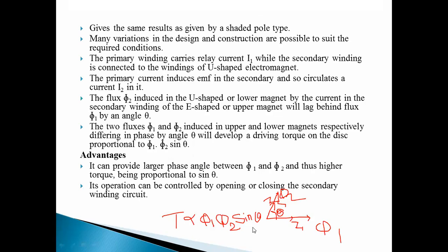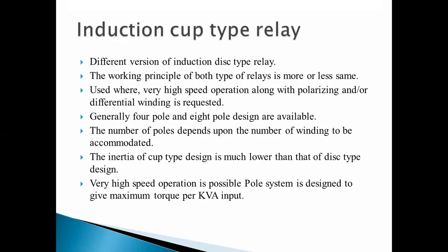So the torque equation is the same everywhere for induction type relays. This is nothing but the equation of the induction motor. You have already studied this, right? It is nothing different. The same equation was there. There you considered the currents, that is torque is proportional to I1 I2 sine phi, and here we are considering the flux.